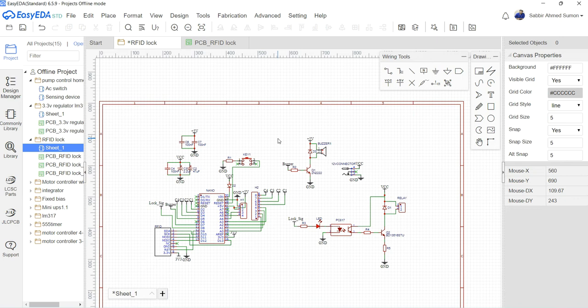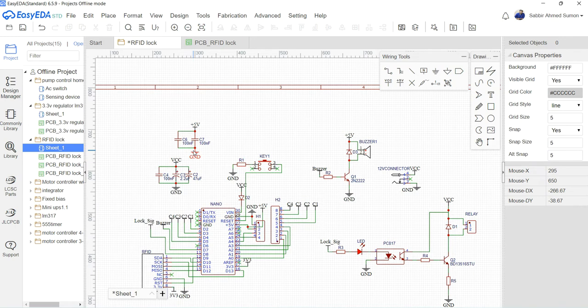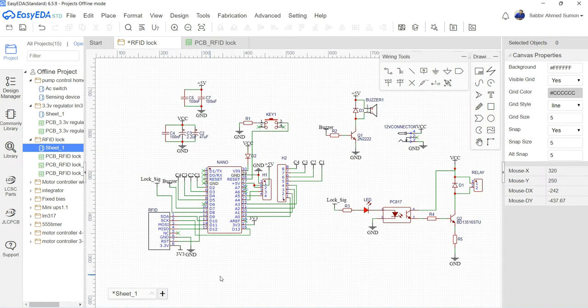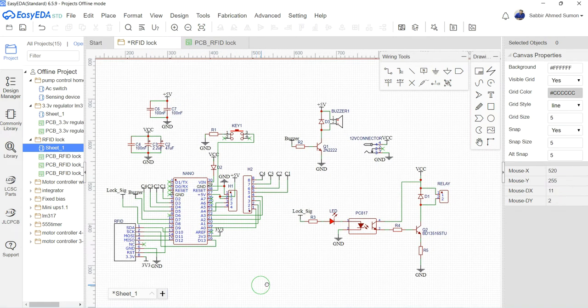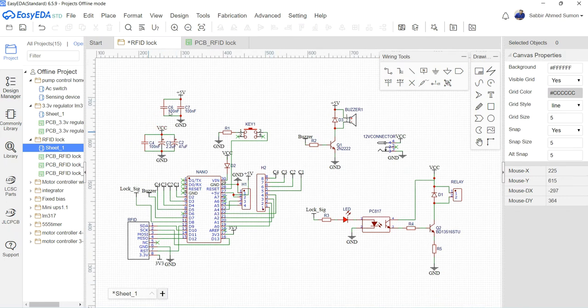So it's not necessary to connect any external 5-volt regulator, but we have connected two capacitors across the 5-volt connector for more stability. The value of these capacitors can be changed accordingly by monitoring the performance, and we can actually ignore all these capacitors if we don't need stability or if we want to lessen the cost.